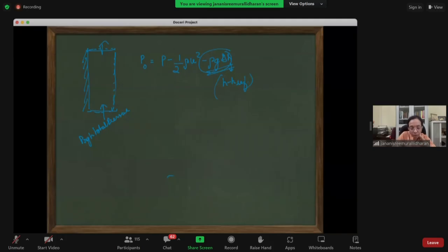So this is helping you set up that rho g h value for the y direction. That is why you're giving this. And you would use the inlet outlet velocity, so that based on the pressure, the velocity will adjust itself.